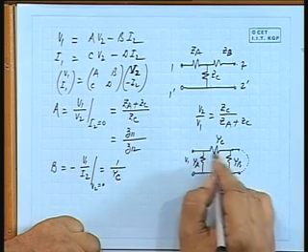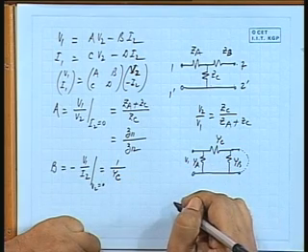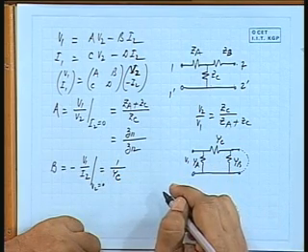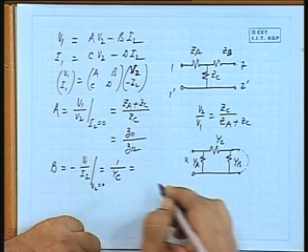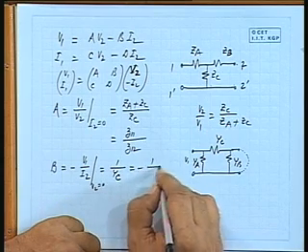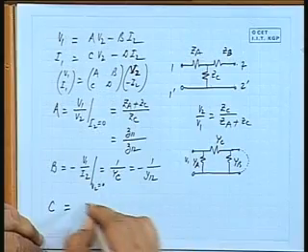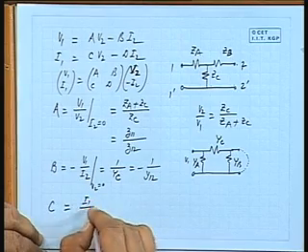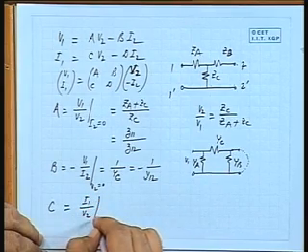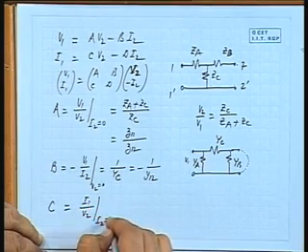And what is YC in terms of Y parameters? Minus of Y12, if you remember, is it not? This was the transfer admittance. C, how much is it? I1 by V2 when I2 is equal to 0, that means again open circuit condition.